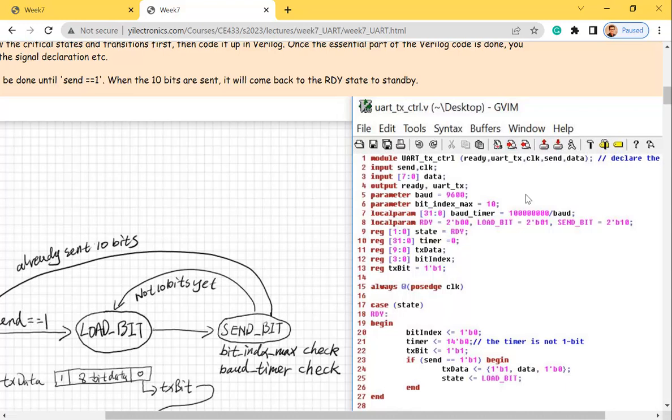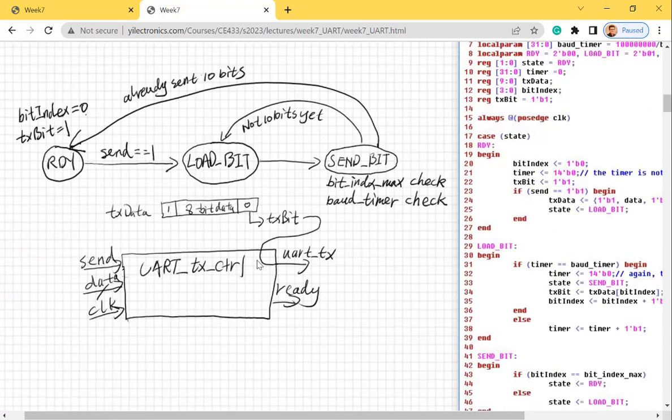So in that case, when we are sending all the bits to here, what frequency should we use? This is the 8-bit data, right? It's 1 byte, and we want to send it bit by bit to here, which is the TX directly connected to the RX. There's no other gates or control logic in between. It's just a wire. Whenever you send it to there, the RX will receive it. It's just one line.